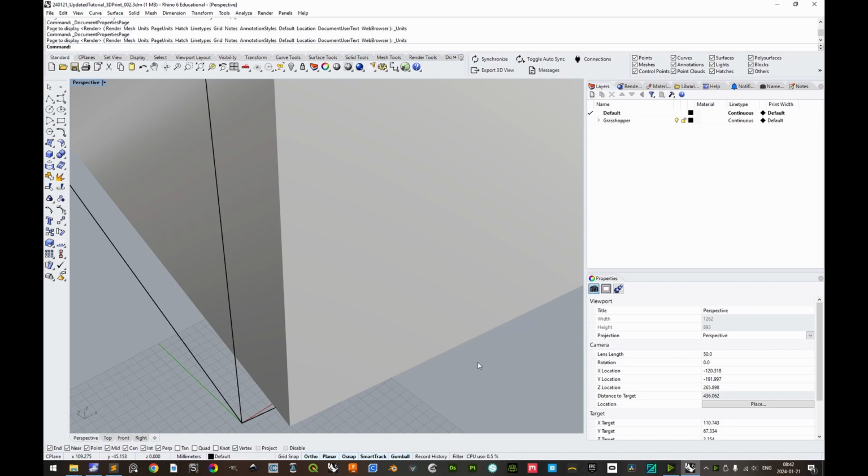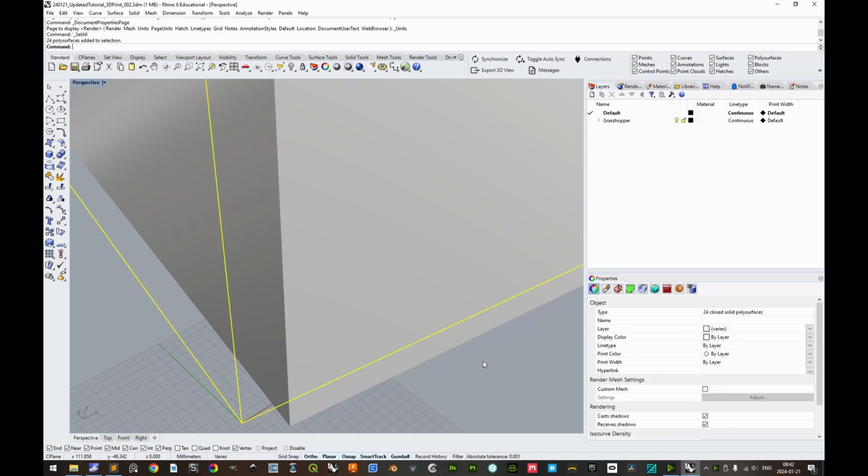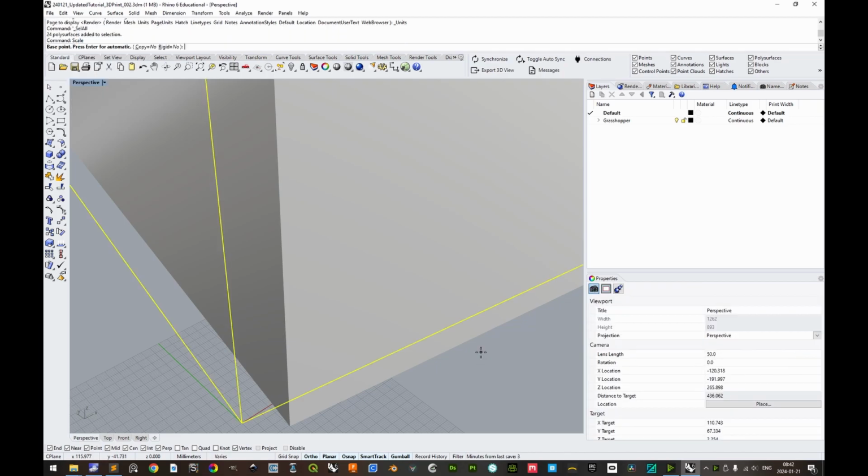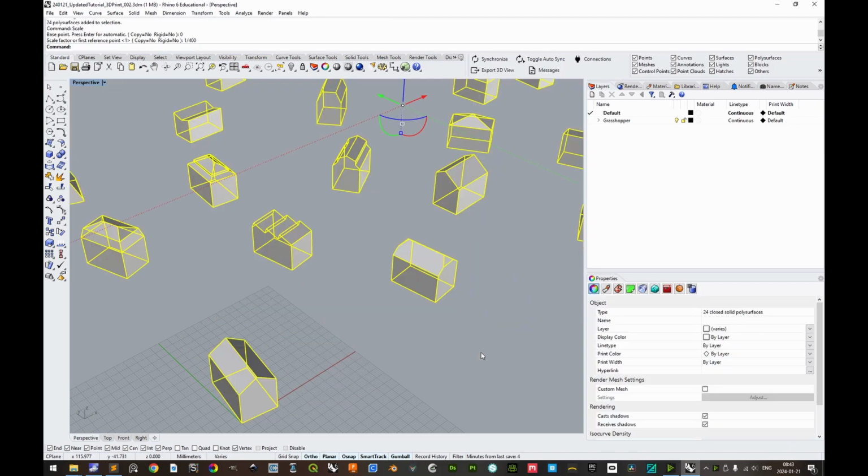With all objects selected with Ctrl+A, enter the Scale command. Base point can be set to 0. Scale factor should be set to your intended fabrication scale. In this case, we want the models to be printed in a scale of 1:400, so we type and enter 1 divided by 400. The maximum dimensions per 3D printer workbed is 200 x 200 x 200 millimeters.